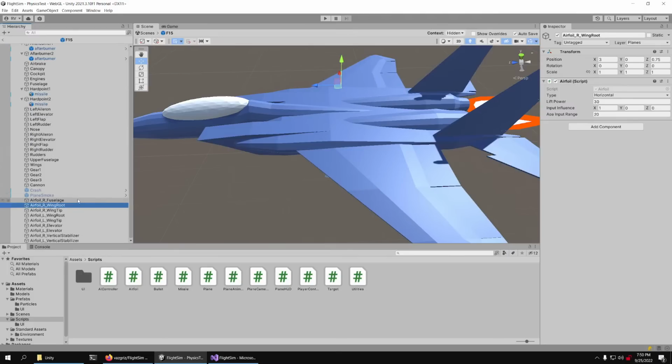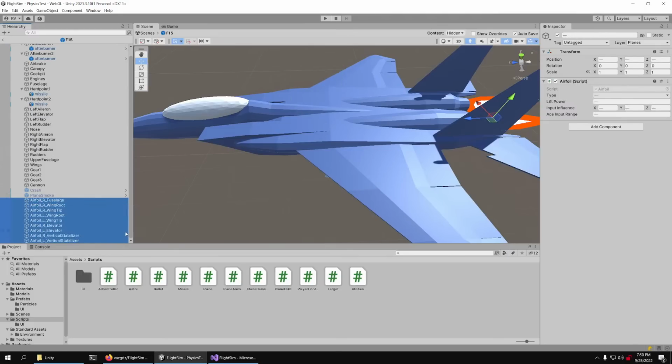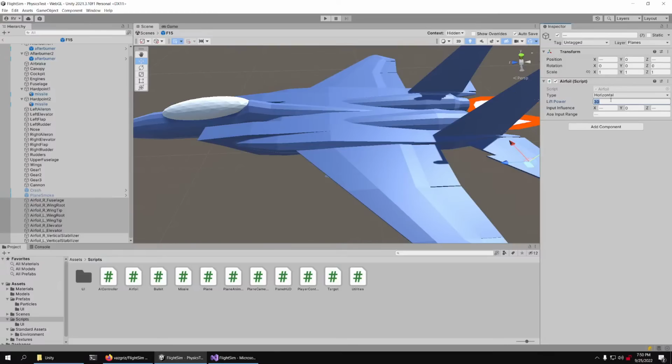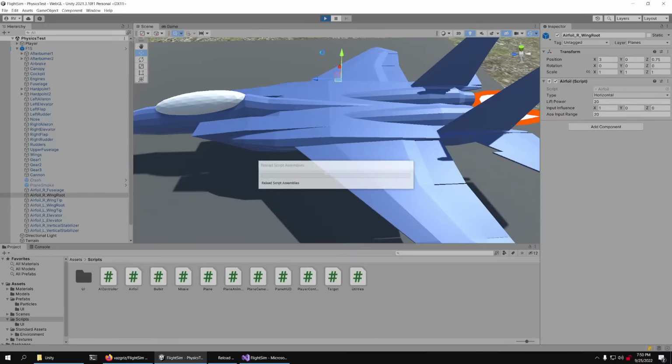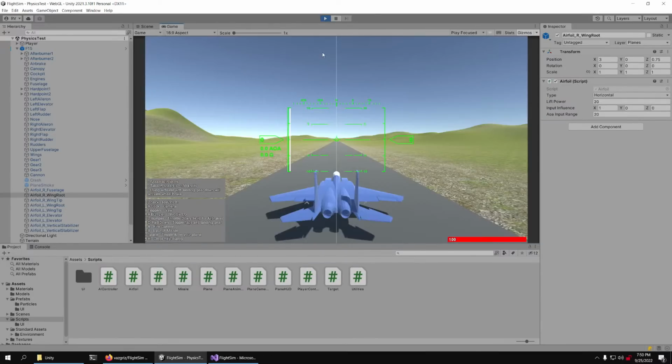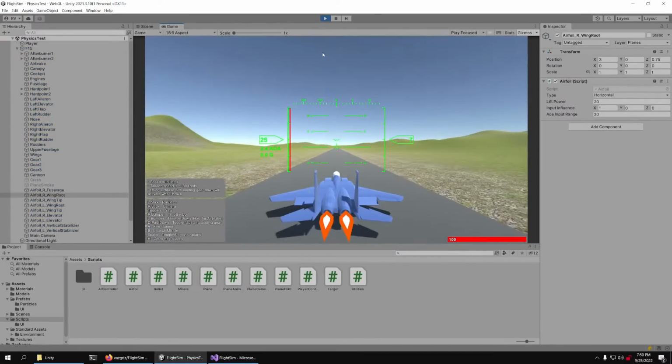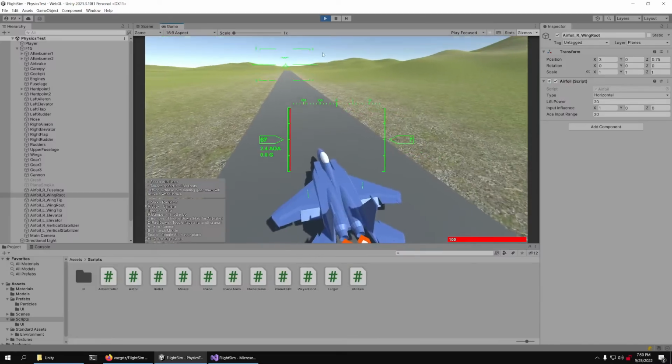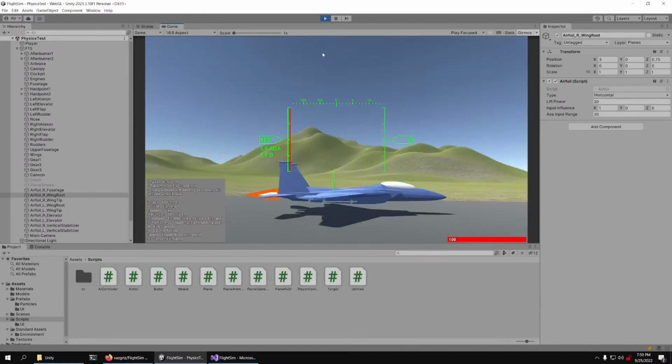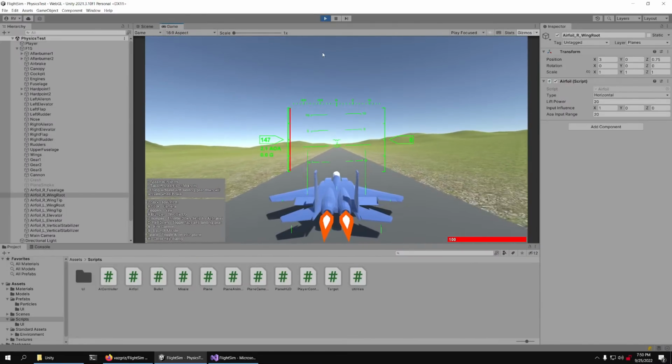So we can probably just turn all of them down, reduce their strength. So instead of 30, let's do 20 here. And the wingtips usually generate less lift to begin with, so let's reduce that even further. It should make their rolls less strong and so more controllable. But we were actually flying there. It was just hard to control whenever you wanted to turn.